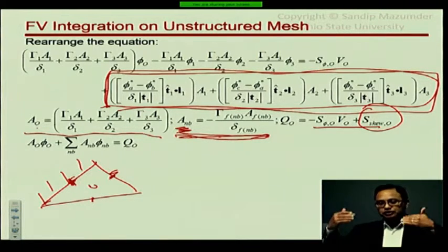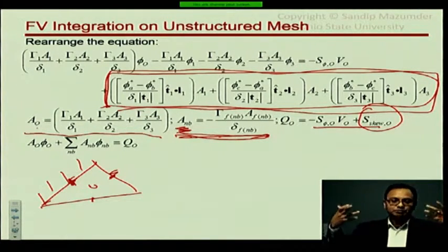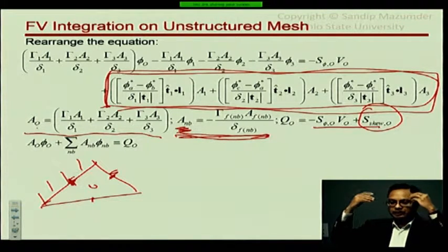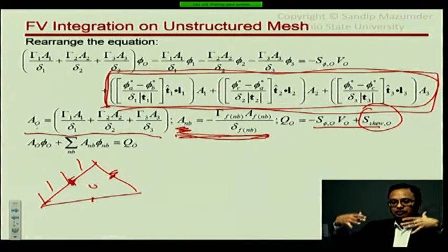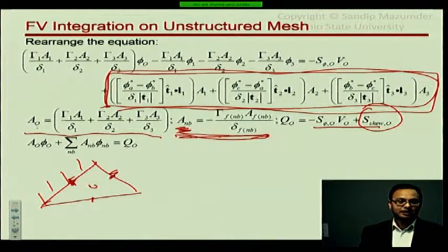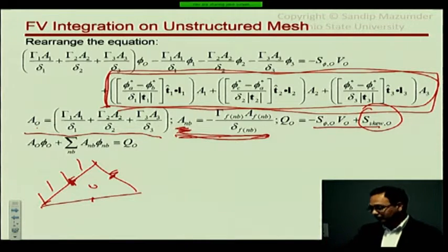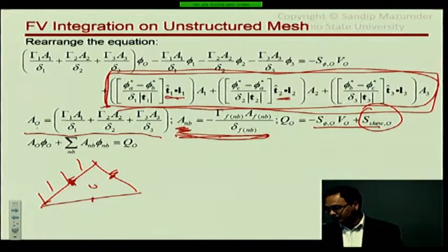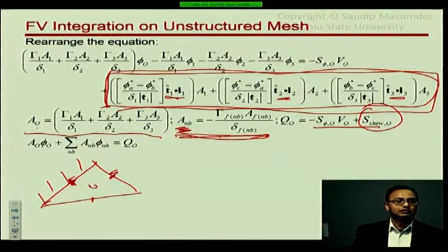So what you will do is if you think about the way you've been setting up matrices, you store your diagonals, you store your off diagonals, you store your source terms, and then you call another function which calculates this skew term and just adds it to the source term. Okay, and it's very easy to test if you make the mesh Cartesian, that should automatically come out 0, no matter what distribution of phi you have, because these guys geometrically are 0. Okay, that's one way to test it. Any questions?